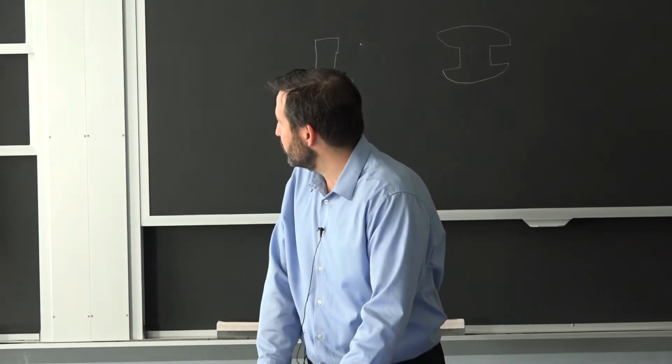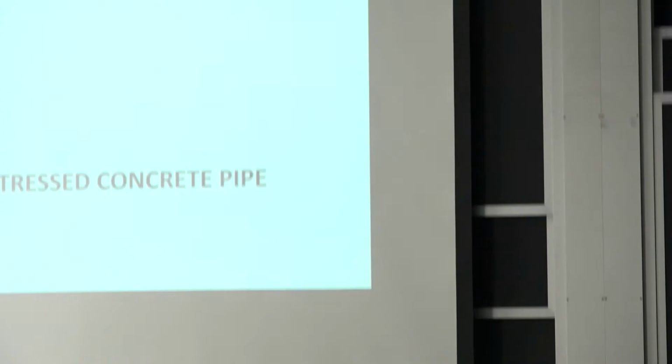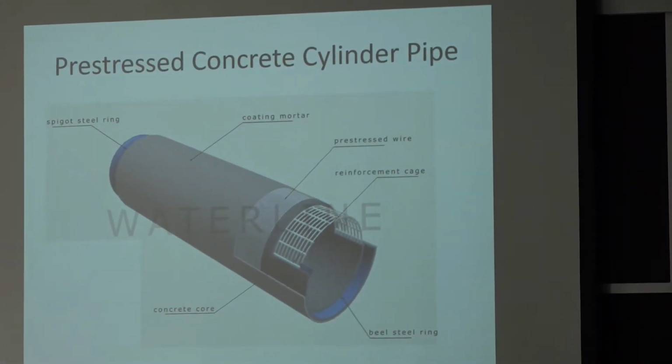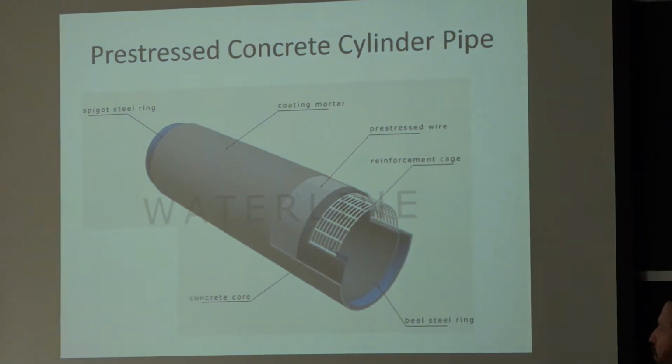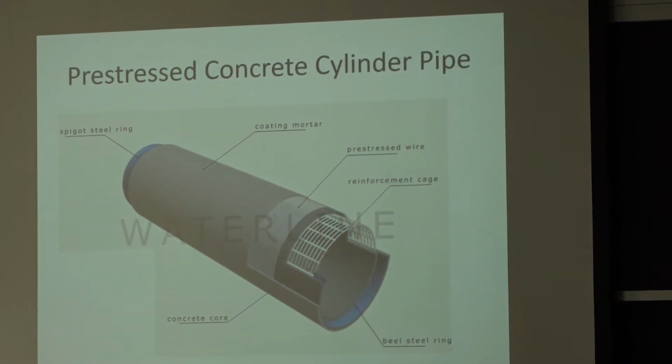And then I'll start talking about welding. So we talked about using high-strength steel in concrete, and one argument was there's only so much room you have to put the reinforcement if you're still going to say you have enough concrete to isolate the steel from the environment. The whole idea here of reinforced concrete, well, there are many ideas. There's cost, but in terms of longevity, you're relying on the stability of the concrete to keep the steel at high pH so it doesn't corrode.